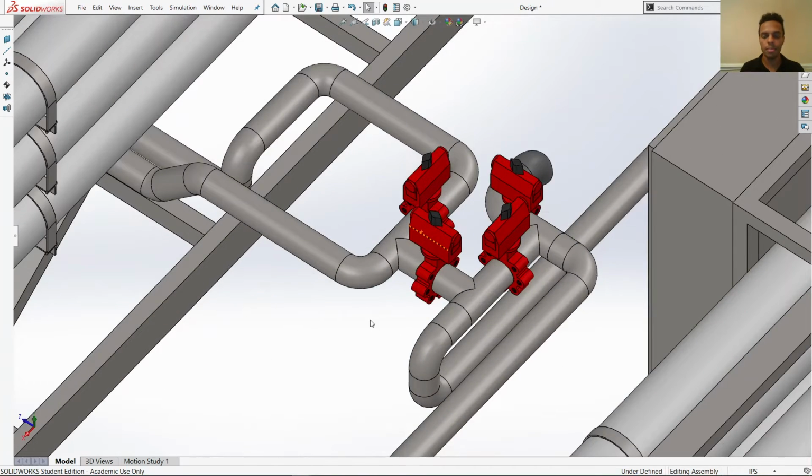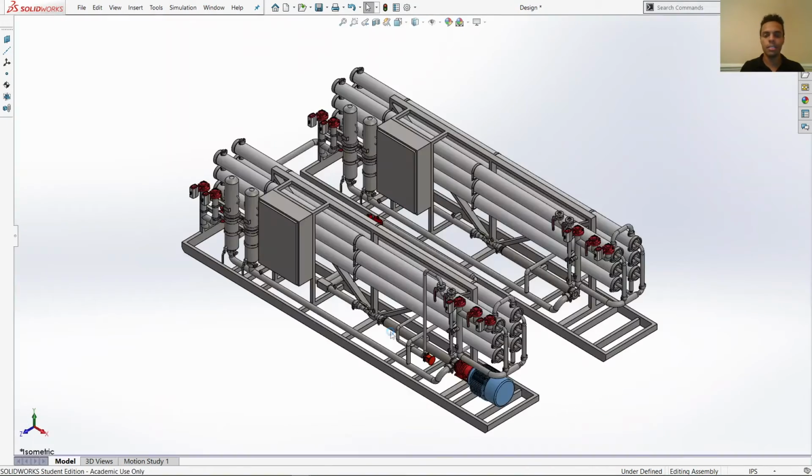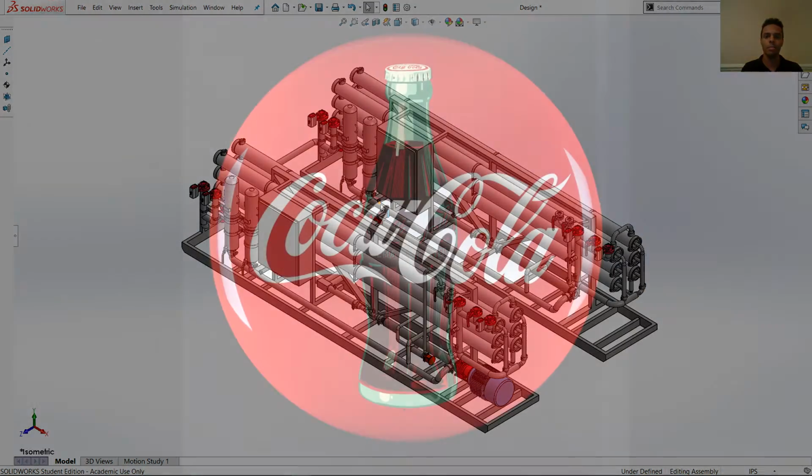This valve manifold, made of gray solenoid valves equipped with actuators, receives the feed water of the system and can send it into Array 1 or into Array 2 based on the mode of operation. This valve manifold also receives the reject water of the first array and can send it either directly to drain or into Array 2 for further filtration based on 2-stage RO design. The biggest lesson the team learned from senior design would be the importance of correctly identifying the critical requirements regarding a proposed solution in order to offer the customer the best solution.